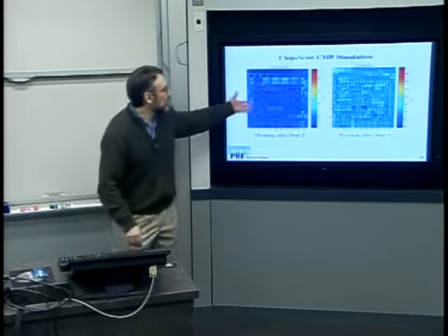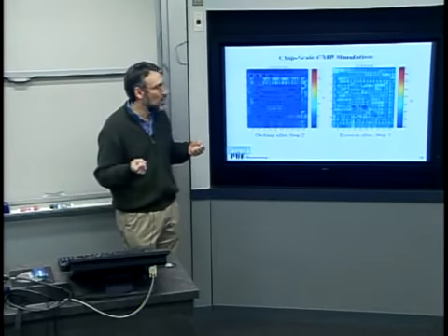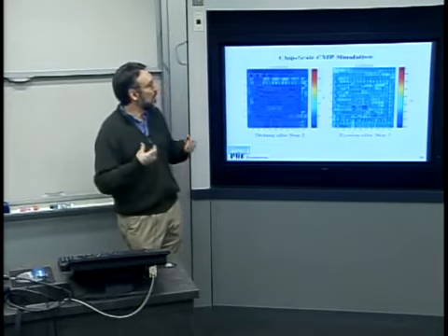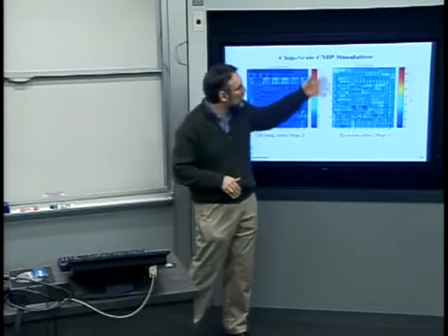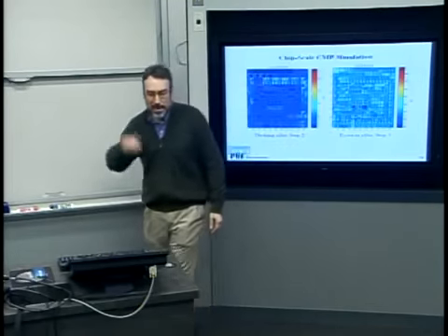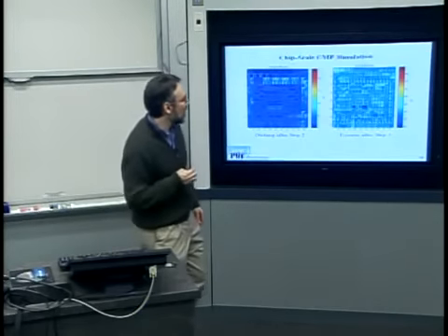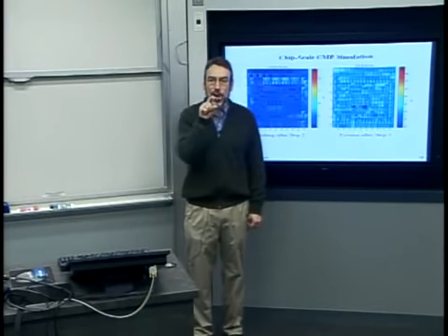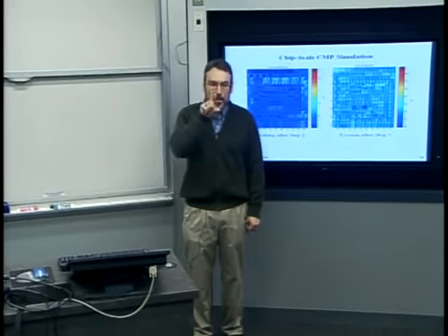But the idea here is this linkage again between design and manufacture, where the manufacturing fab can characterize what the actual amount of dishing or erosion is going to be for very complicated product chips. And that information could get fed back to the designer so that they actually know in this location, my final copper wire is going to be this thick, not this thick.